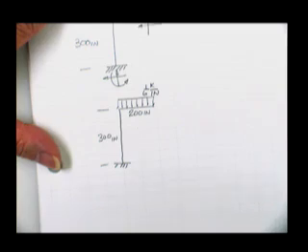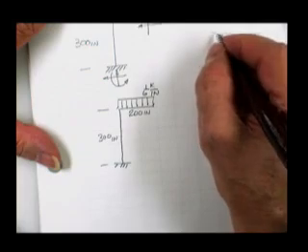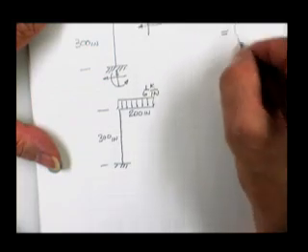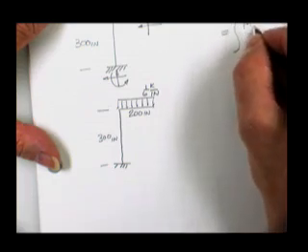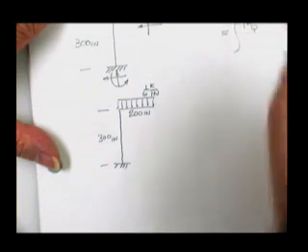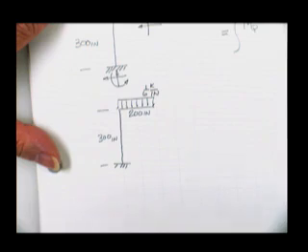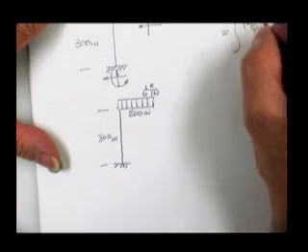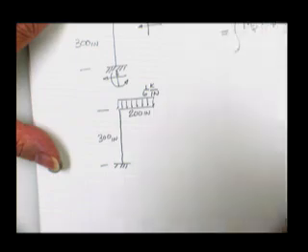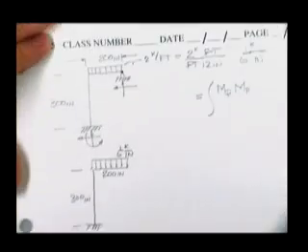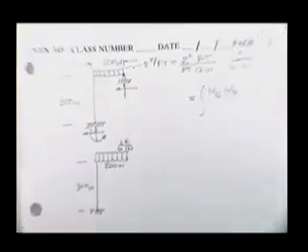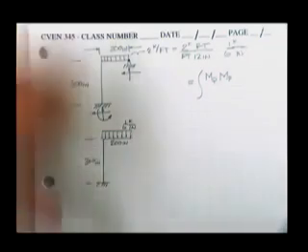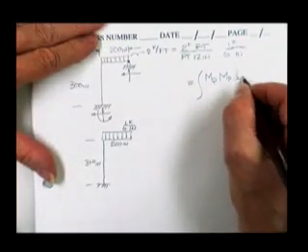As you know, in order to get the deflection, you're going to have to integrate all of these members, M, due to the unit load that you decide to put on the structure at a place you decide where to put it, in a direction you decide which way it ought to go, times the real, times dx over EI.